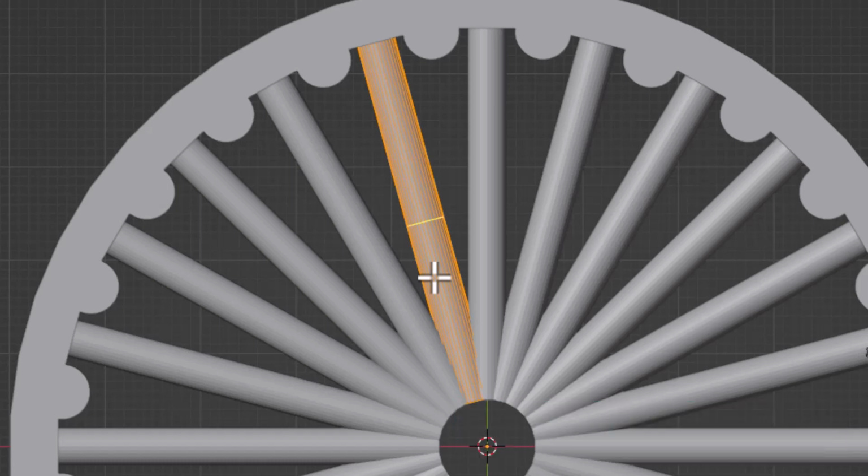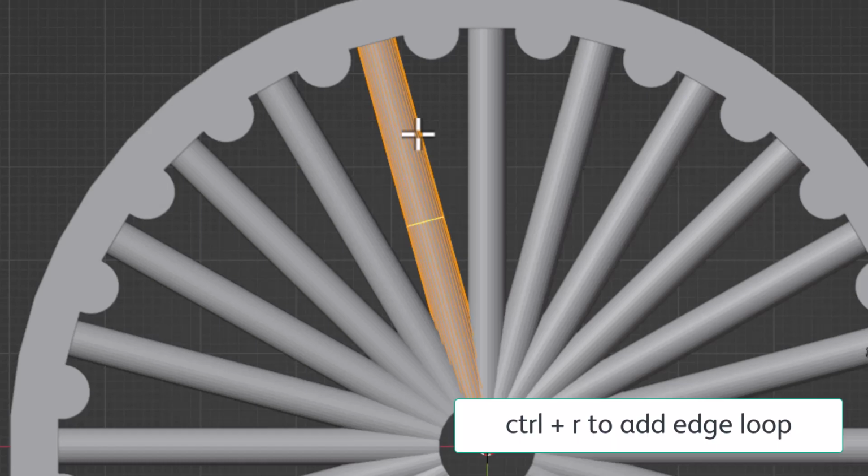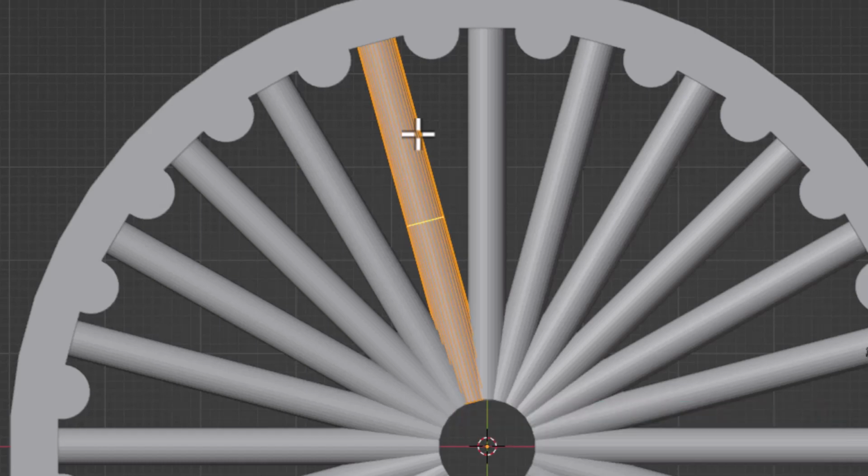In the original mesh, now what I will do is press Ctrl R. See, Ctrl R means you are going to add an edge loop. You can see I have added one new edge loop here, and if I roll the mouse twice, you will have 2. If I roll again, you will have 3. These are called edge loops. We are going to discuss it in detail in our next lesson. I will just right click to cancel it. As of now, I will again press Ctrl R and add only one loop.